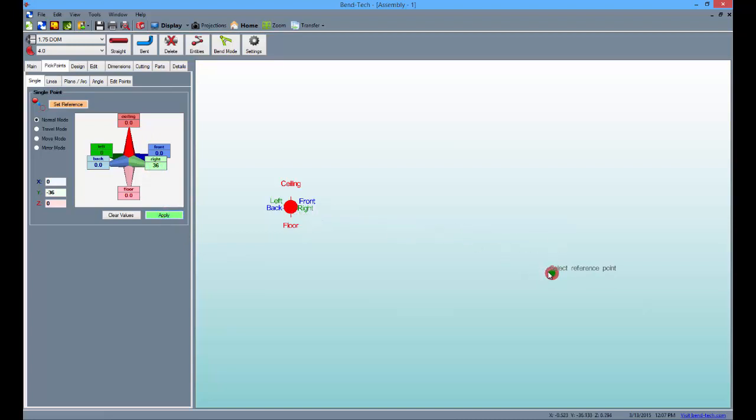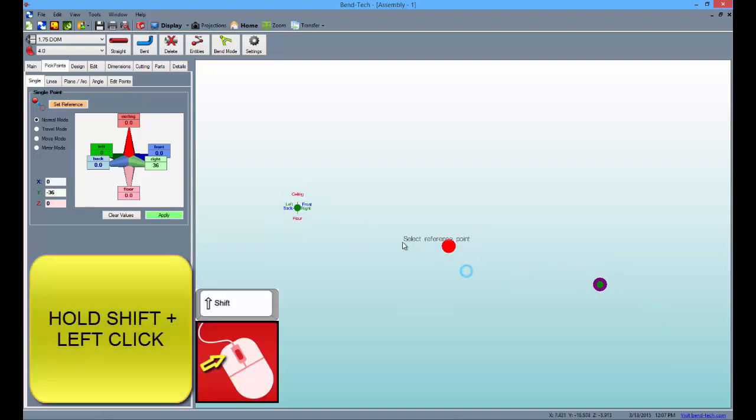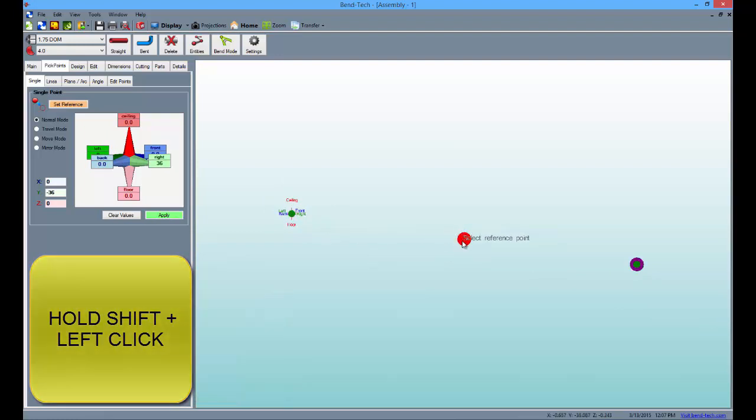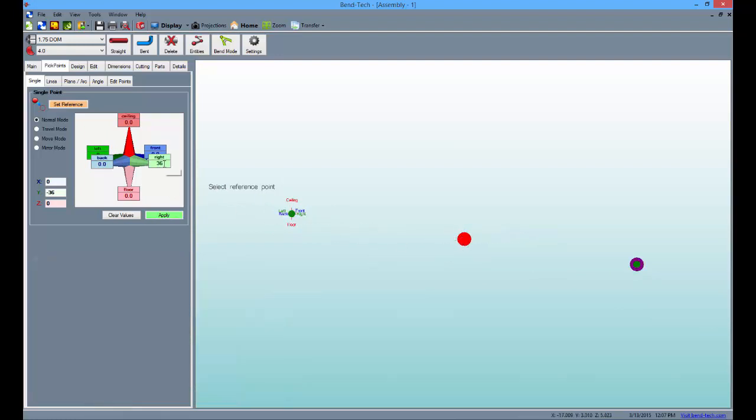You'll see a point made 36 inches to the right of the TriStar. Shift-click this point to create another point 36 inches to the right of that. Now, you can enter up to 3 lengths into these value fields at the same time, as long as they don't conflict with each other.